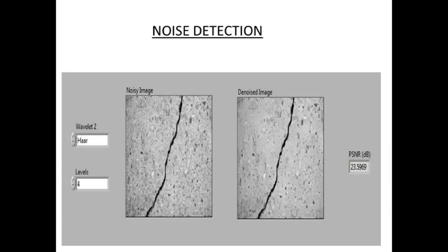The next stage is denoising. Image denoising is used to remove additive noise while retaining as much as possible the important signal features while preserving edges. One common approach is to use a Gaussian filter. Firstly, it applies the wavelet transform to the noisy data and obtains detail coefficients and approximation coefficients.